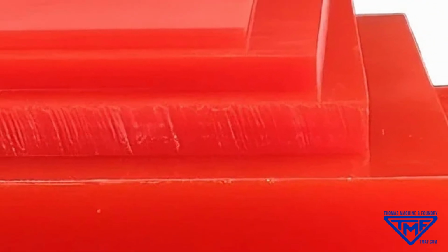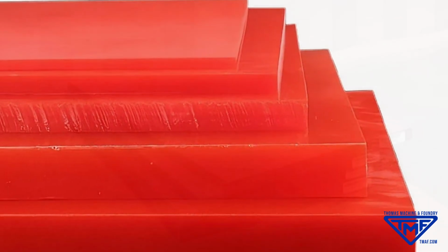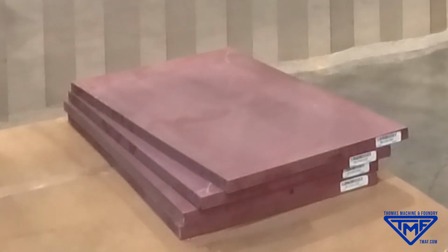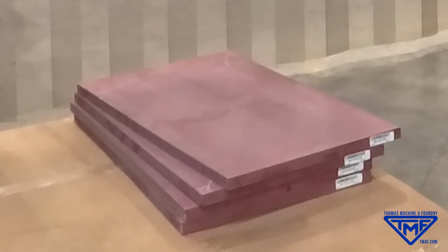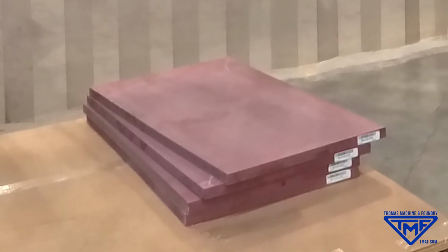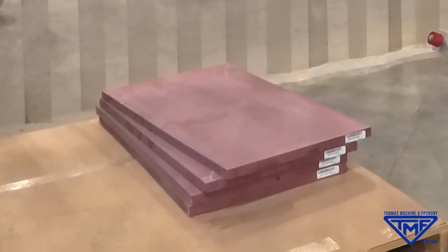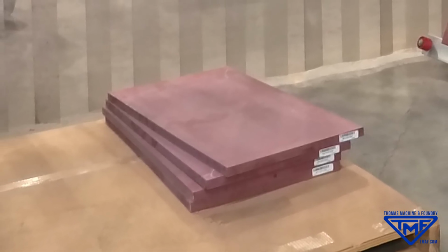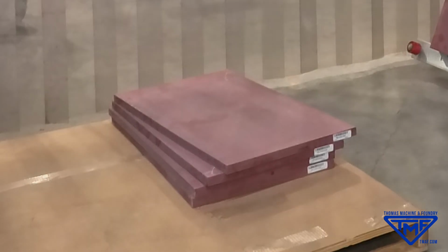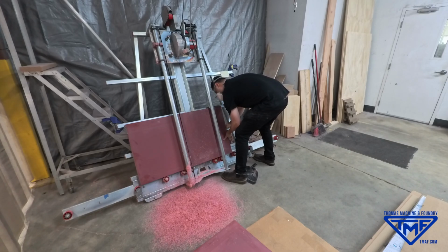These sheets come in a variety of sizes and thicknesses, from 1 inch all the way up to 6 inches thick. For most patterns, we use thinner 1 and 2 inch material, not because thicker material isn't available, but because using thinner sections allows us to be more efficient. It reduces wasted material, it makes the pieces easier to handle, and it gives us more flexibility when building large, complex patterns. The first step is cutting these large sheets down into manageable pieces.